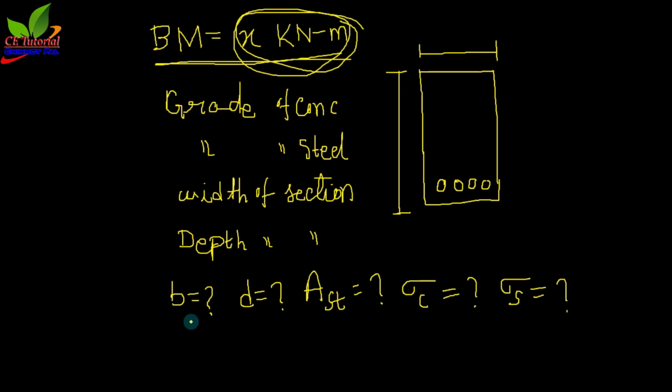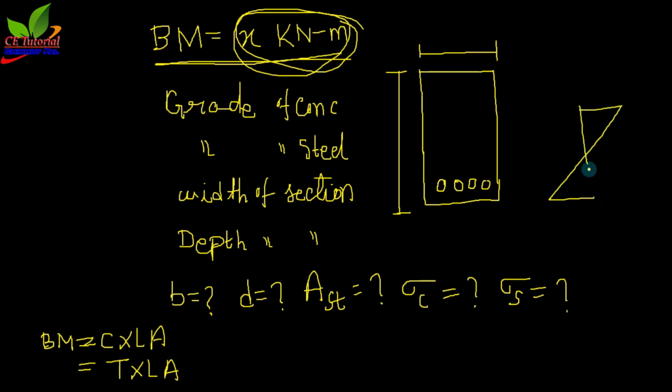Okay, now you have some formulas. One formula is that you can apply bending moment equals C into lever arm, and another formula is T multiplied by lever arm. Okay, and you can create another formula from the bending stress diagram.